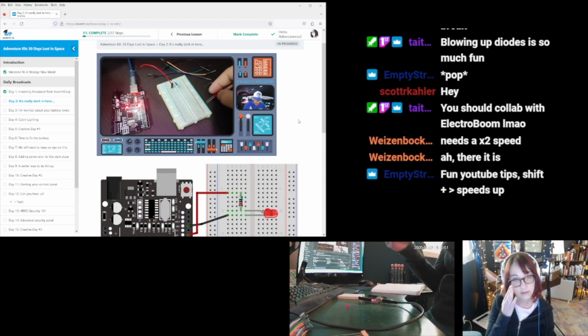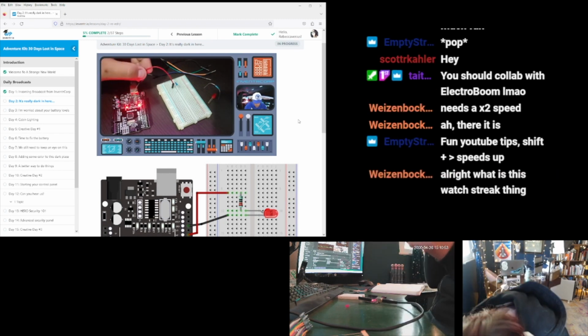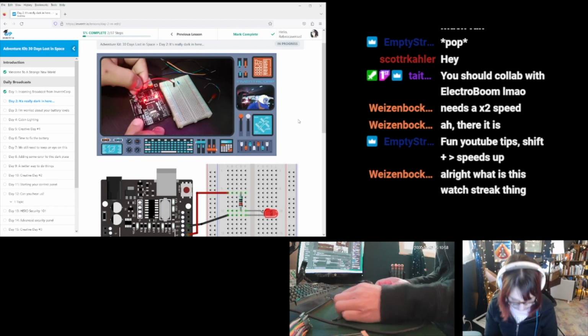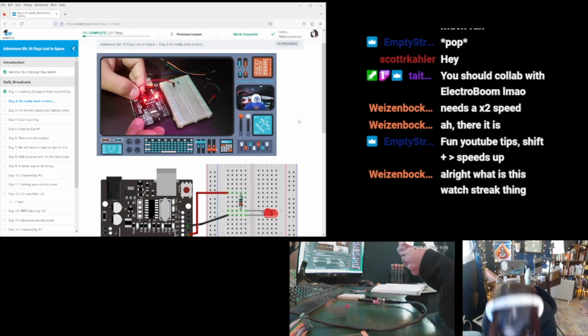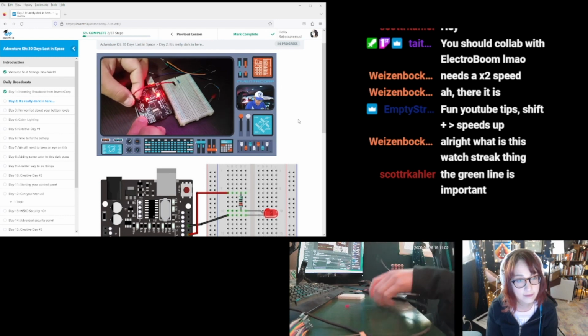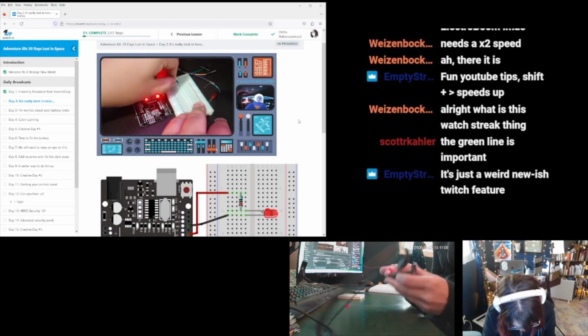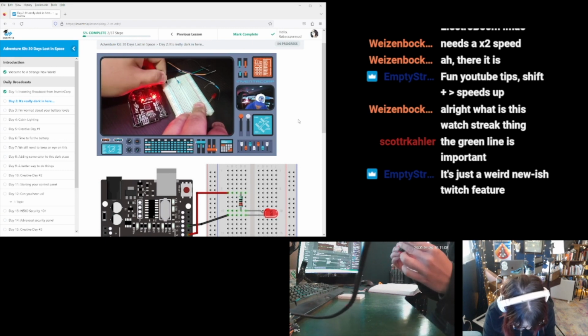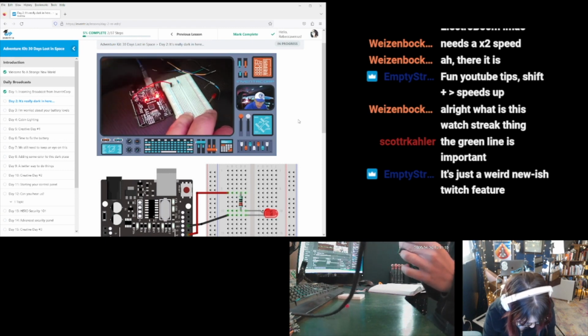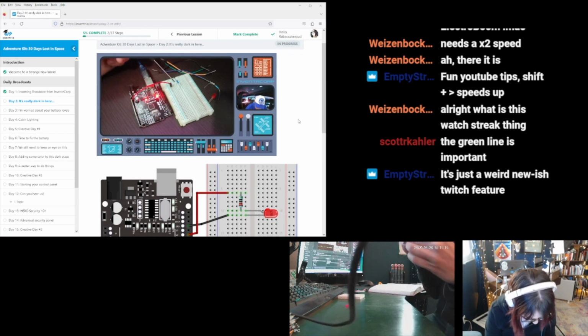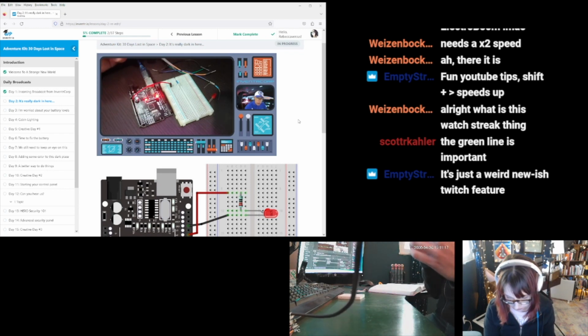it to illuminate. Now, as I mentioned before, there's a pin on the Hero labeled 5V for 5 volts. So we're going to take a wire and connect it to that 5 volt pin, and then connect that wire in turn to a particular row here on the breadboard. In this particular case, I've chosen to connect it to row number 6. There's nothing important about that. I just pick it at random. Also connected to row 6 is one side of this resistor, this 220 ohm resistor.